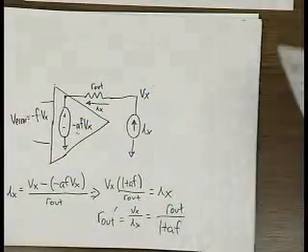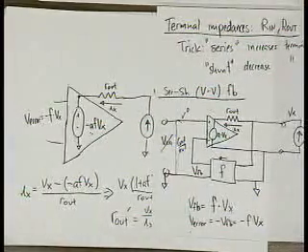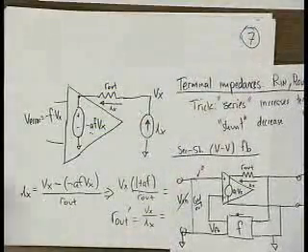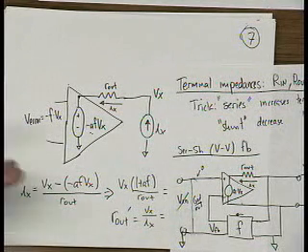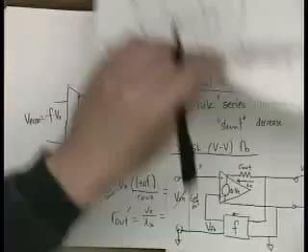What do you do in order to calculate the output resistance? You ground the input. Okay, and so you can do this with all sorts of networks. I gave you a real simple one, where it's clear that it's voltage feedback. But in reality, you're going to be given circuits where it's not so clear what kind of circuit it is, and hence what you're supposed to be doing. And that's where this stuff either gets tricky or fun, depending on your perspective.